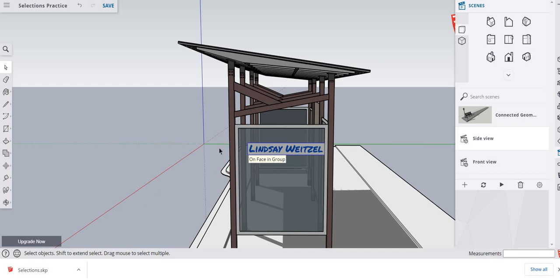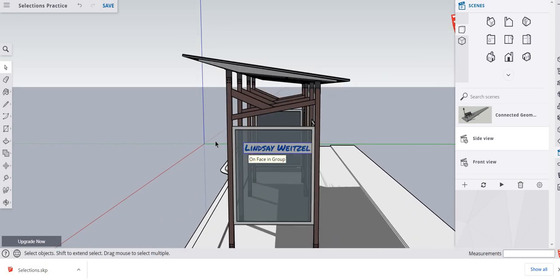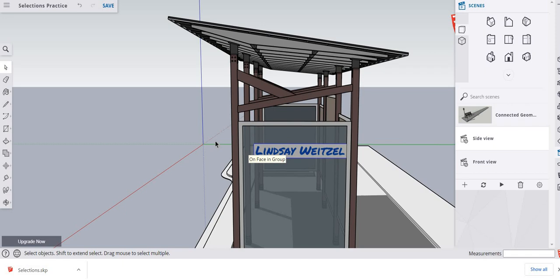Okay, with that pasted there, I'm going to zoom in a little bit and play with the selection tool, trying to get some kind of grouping here. If you drag from the upper left corner and then go to the lower right corner, you see we can drag a box around this and it will only select the geometries that are completely inside that box. So I'll do that again. Even though I'm doing all these different pieces, it will only highlight things that are completely bounded inside this box.